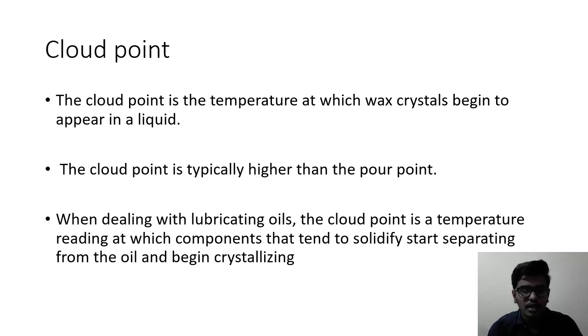When dealing with the lubricating oils, the cloud point is the temperature reading at which components that tend to solidify start separating from the oil and begin crystallizing. Here they are saying that the cloud point is typically higher than the pour point, and the cloud point is the temperature at which wax crystals begin to appear in a liquid. That is called a cloud point.